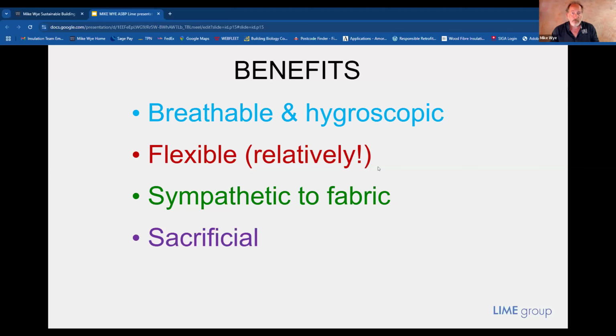If we've got cement pointing, for example, on an older wall, brick or stone, the hardness and the relative brittleness of that cement, as well as its impervious nature, tends to mean that we may have cracking appearing due to minor movements in the structure, and those movements are much better accommodated by a slightly more elastic mortar, for example, made with lime. Therefore, we can have an increasing mechanism and cycle of water ingress into the wall, which can then only pass through the brick or the stone because the mortar itself is largely impervious.